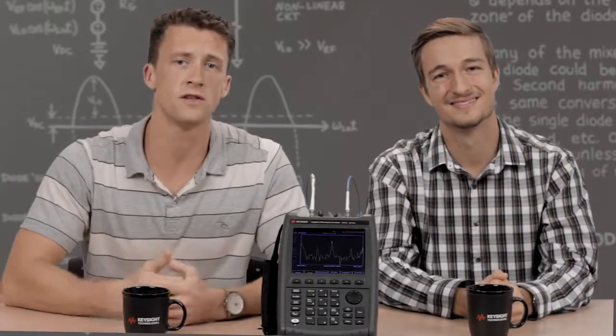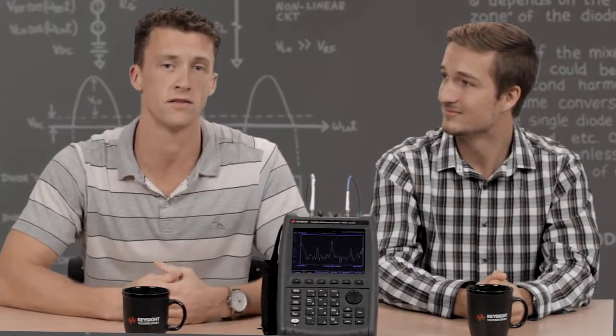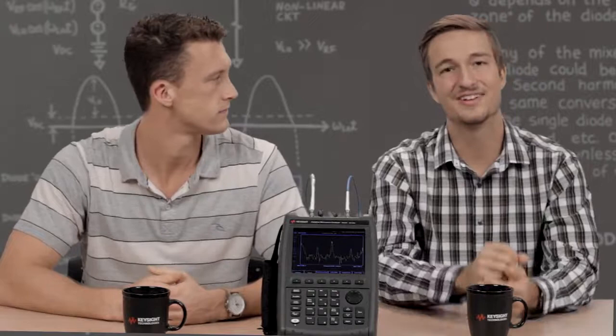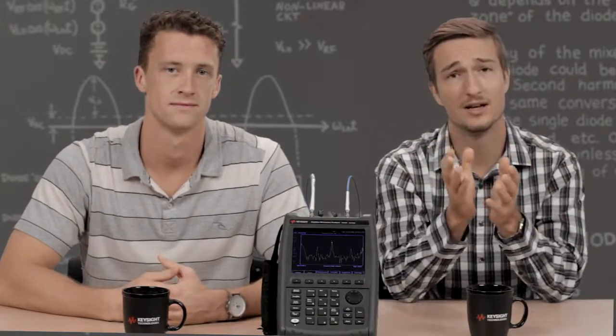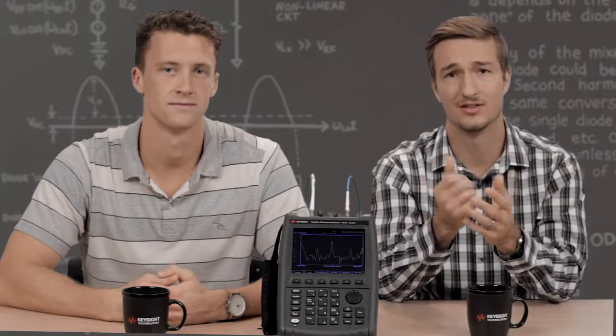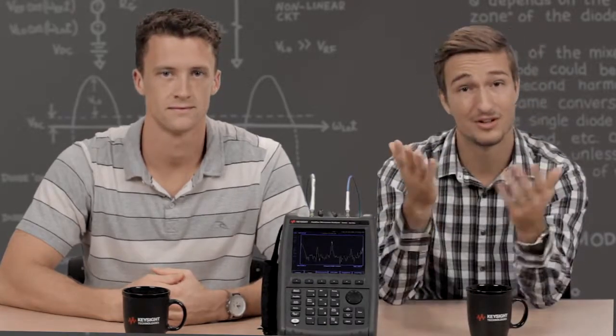What we've put together for you is a series of 10 episodes that goes over just the basics of the FieldFox. See, the FieldFox is kind of like the Swiss Army knife of electronic measurement. Exactly, and just like a Swiss Army knife, the FieldFox is a small, portable, lightweight instrument that can do a whole lot of things. It can be used as a network analyzer, as a spectrum analyzer, as a real-time spectrum analyzer, a cable and antenna tester, and much more.